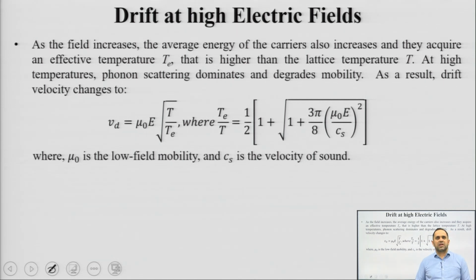So, either charge carriers start to move around, they start to travel fast, and then the chances of collision also start to increase. Now, in addition to these charge carriers, the extra energy which you are supplying in the form of electric field may also get transferred to the stationary ions and atoms. These atoms start to vibrate, they can't move, which is known as a phonon.